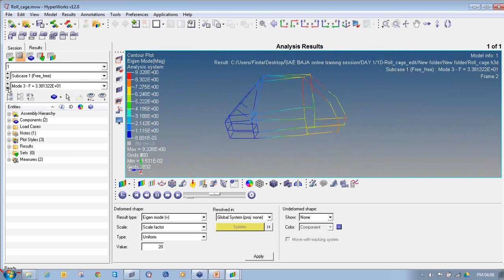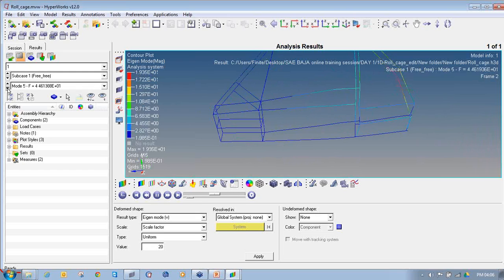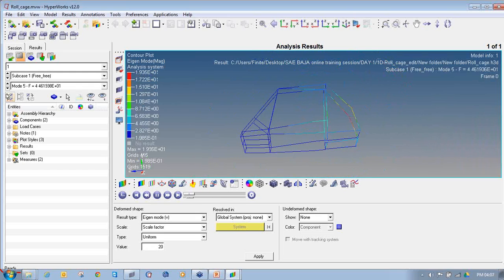You can see here all my pipes are now properly connected. This is the most important thing: all the segments should be properly connected. If not, you have to connect them manually the way I have shown you. Just delete those elements, connect from node to node, create new elements, and check again whether all these beam sections are connected properly or not.